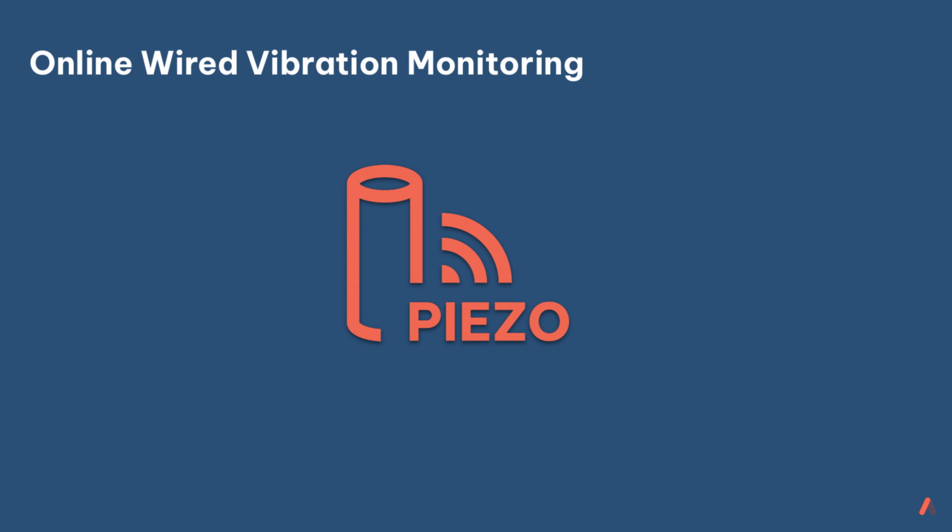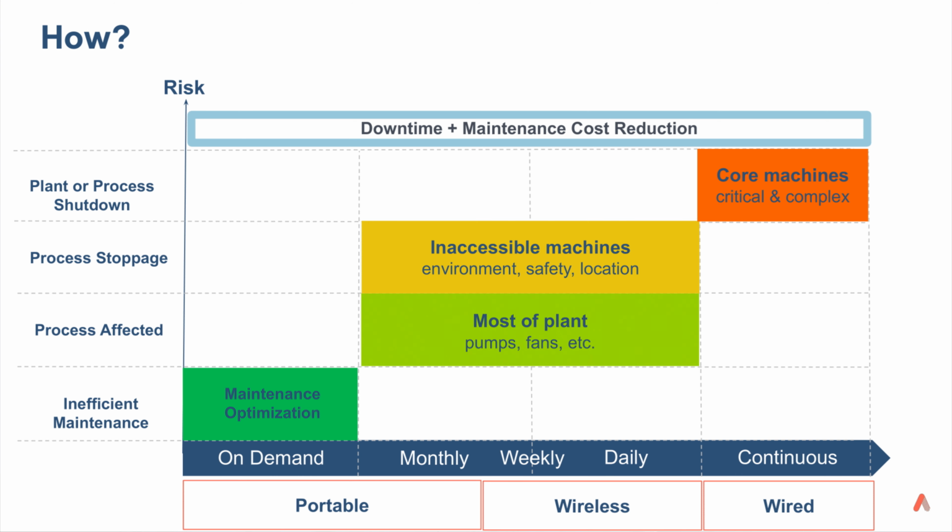That better option would be an online wired vibration monitoring system. This could use your traditional piezoelectric sensor. It could also use prox probes, temperature, thermocouples, anything that you could feed data into, and basically give the operator more actionable data so that they can make choices and decisions and analyze. So when we look back at our chart to decide, well, where do we need to use a wired system?